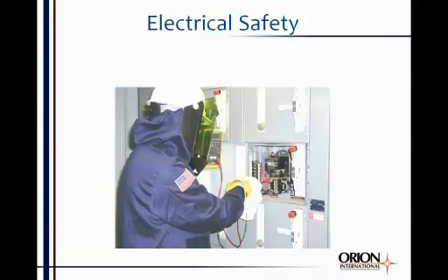Okay, here's what we're talking about for doing voltage testing in the industry nowadays in a motor starter. This guy's doing a voltage test in a motor starter. He has on voltage-rated gloves, that's the leather gloves you see, with leather over protectors on top of those. The leather protects the rubber voltage-rated glove.